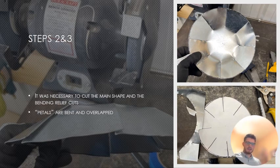So the next steps are to cut out the main shape, which you can see here, with tin snips, and to also cut out the bending relief cuts, which you can see are also cut out here and here. That is basically just done with tin snips, which are essentially scissors for metal. And then the edge was refined with a sanding disc on a grinder, just to keep that outside diameter consistent with the design.